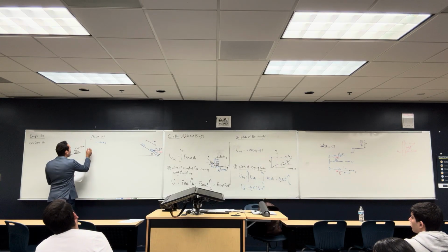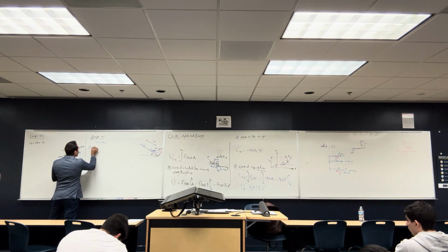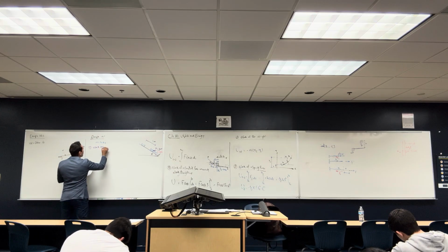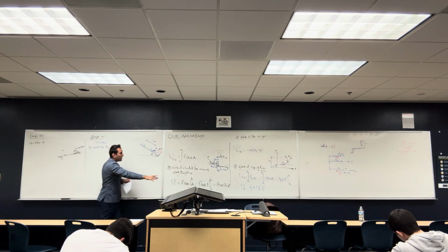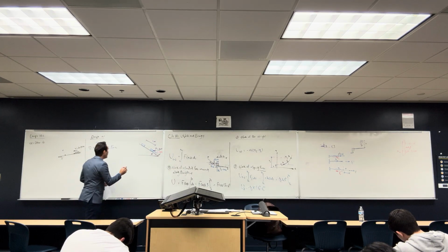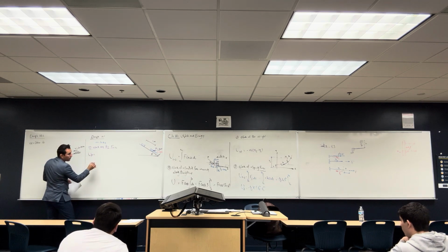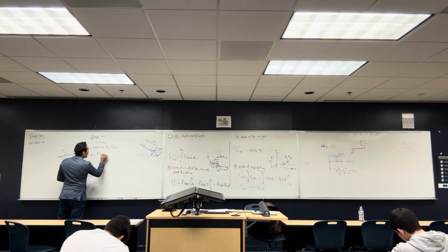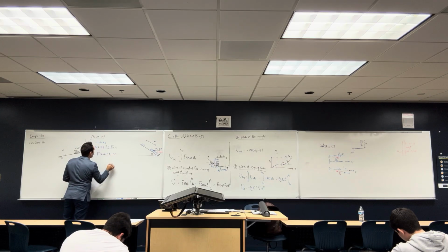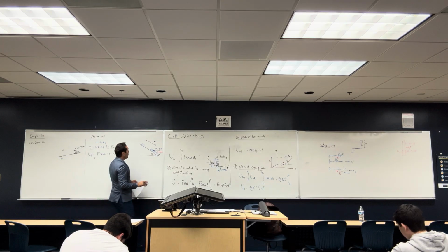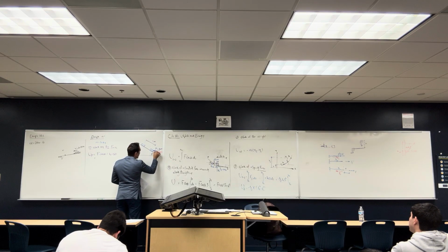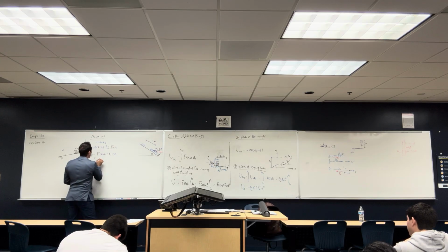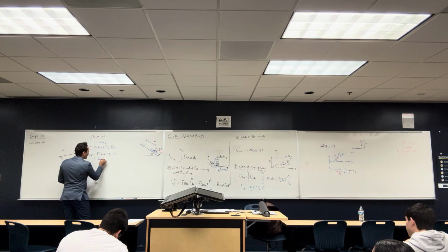The first one I want to find, number one, is the work done by the horizontal force. Since the horizontal force is constant, I can apply this rule. The U done by B is equal to F cosine theta multiplied by S2 minus S1. First I have to find F cosine theta. Theta is 30 degrees, so it's going to be 400 cosine 30 degrees.